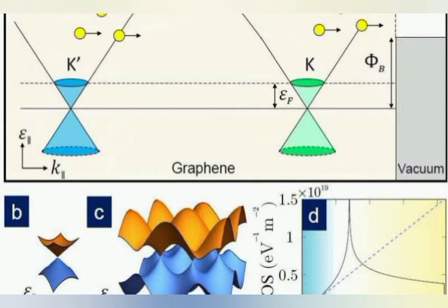The more negative this potential is, the more electrons will be repelled from the grid, and hence fewer electrons will reach the anode and the screen. The number of electrons reaching the screen determines the brightness of the screen. Hence, the negative potential of the grid can be used as a brightness control. The anode is connected to a positive potential and hence is used to accelerate the electrons. The electrons are focused into a fine beam as they pass through the anode.